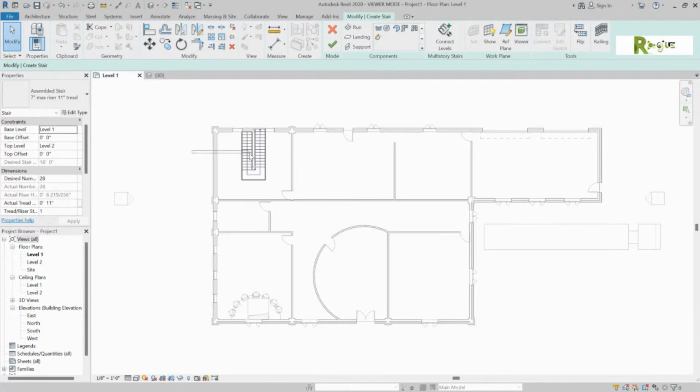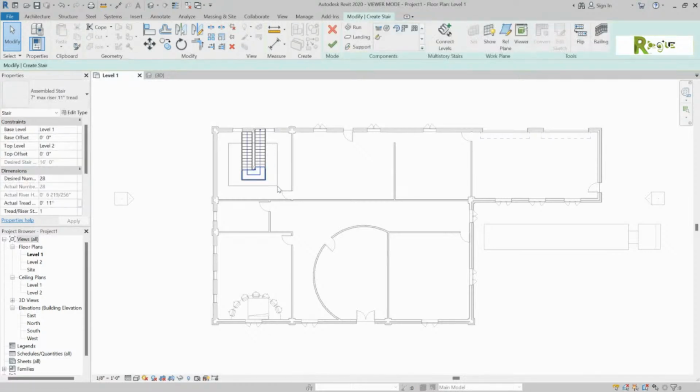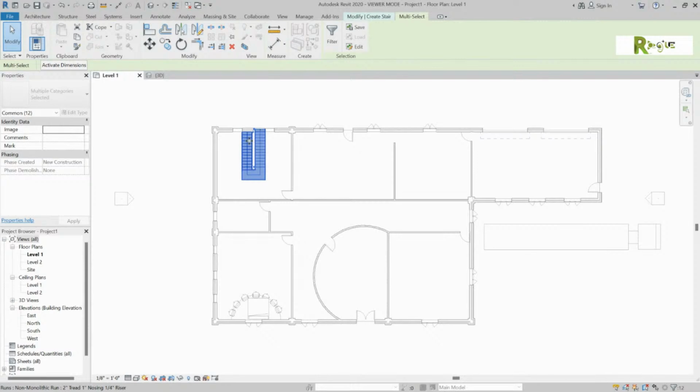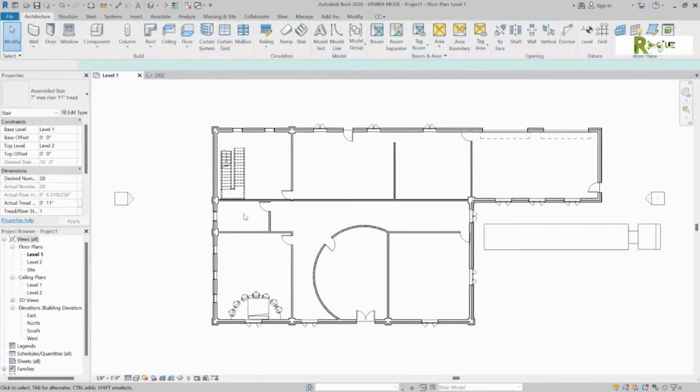And click. Do you see how that window that you're drawing is solid? That means it's only going to pick things inside that window. So you would have to be in that direction is crossing. There you go. So now you could nudge this down into a corner. You might rotate it. When you're done, you're going to hit the finish sketch. And it will have drawn that stair.